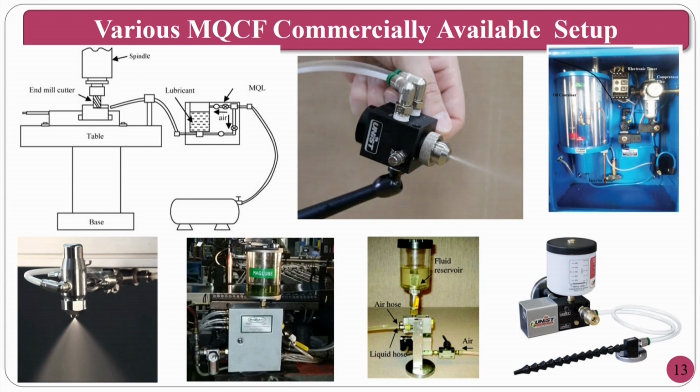If at all you have some money, you can go ahead with purchasing of the nozzles. Here you can see the nozzle system where the cutting fluid is there, as well as the air is there, both are mixing internally and sending the mist like this. So this is one of the systems. At the same time, you can have other systems also where you can mix internally and send the spray like this. Everywhere it is a spreading one.